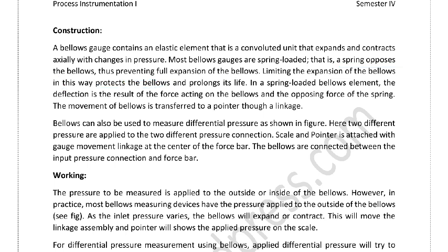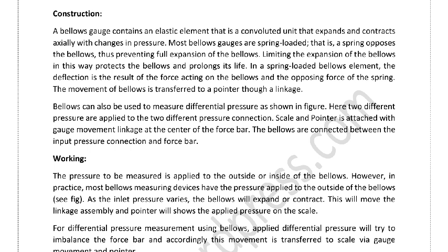and prolong its life. That means the spring is connected with the diaphragm, so that it permits only the maximum expansion of the bellows, so that its life expectancy is extended and it will not be damaged if more pressure is applied.